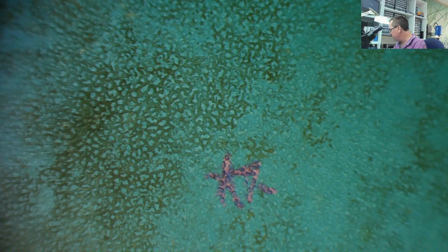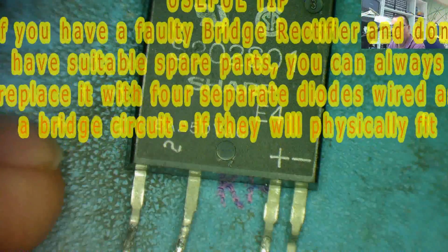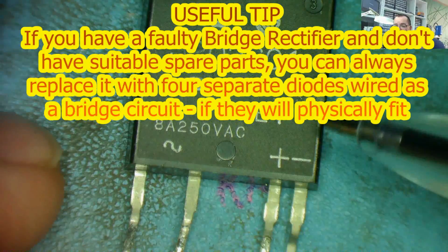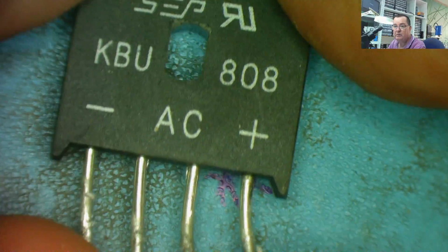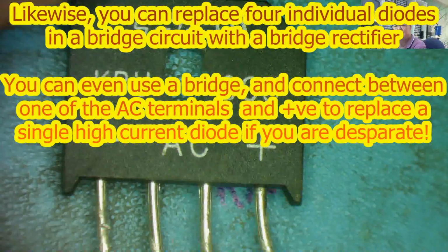Let's have a look at some bridge rectifiers. This is a bridge rectifier, encapsulated in one, not just 4 diodes. This is marked 8 amp 250 volt. This is your AC coming in, and this is your plus or minus. So that's a typical one. Let's have a look at another one. So AC on the 2 middle pins, plus and minus.